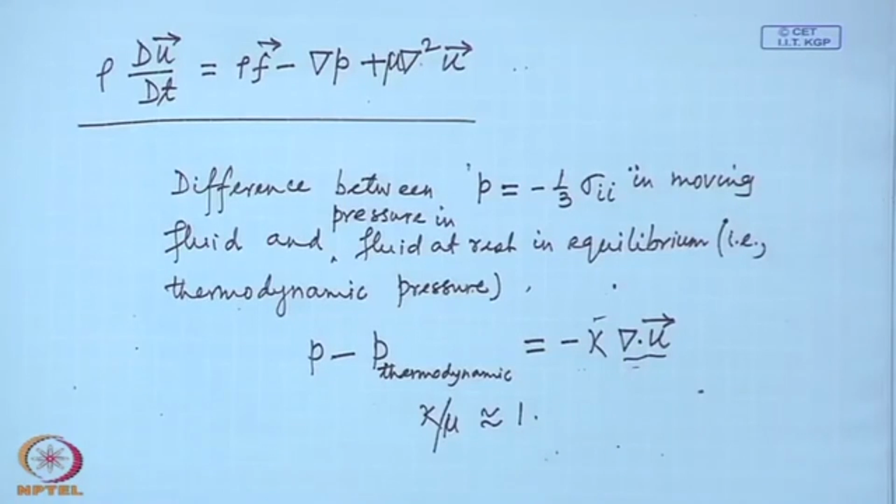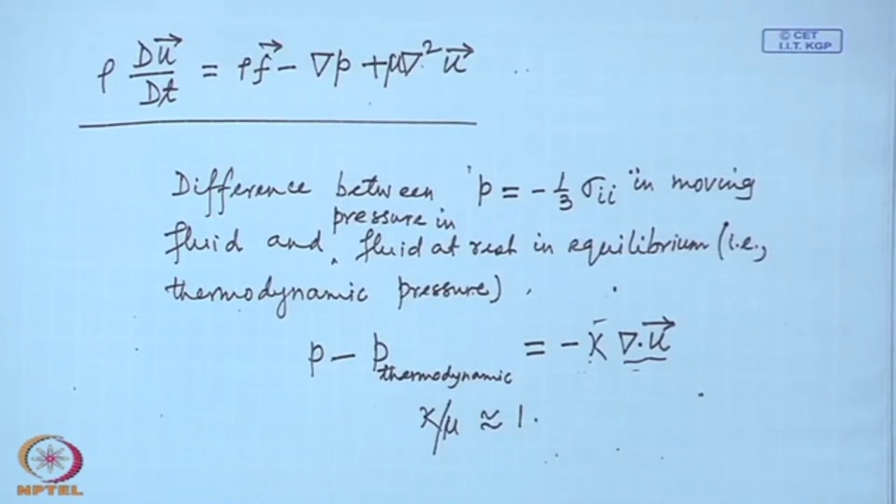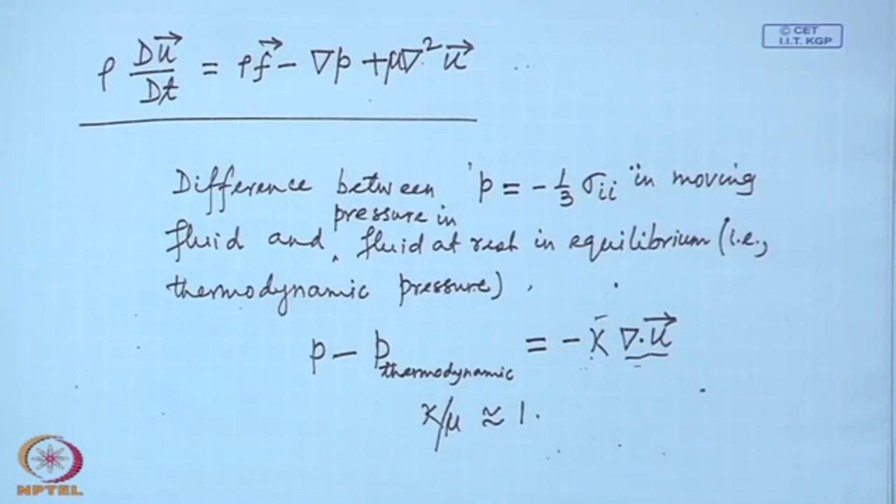However, when the rate of expansion is non-zero, as in the case of a compressible flow, there is a difference, but again this quantity being very small, even though the rate of expansion is larger, still the difference is very small. However, there are some cases where the rate of expansion approaches an extremely large value, then of course, this is considerable.